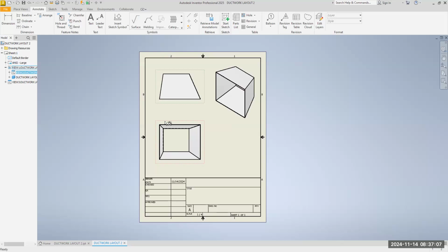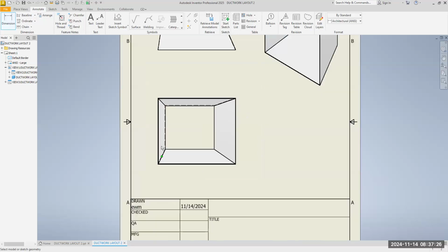And we are going to go to dimension. But when you click on dimension, come over here to your far. It's really weird that they have it so far away over here. But select dimension, come over here and arrow down and select architectural. So this is new.